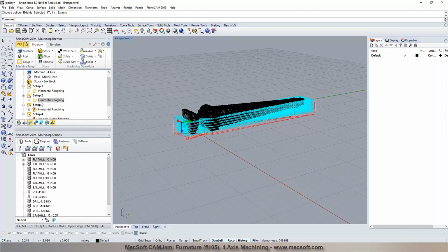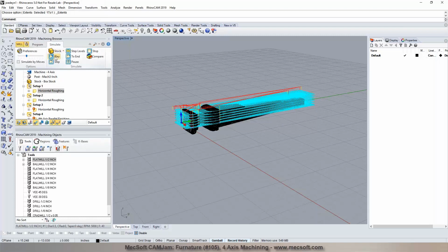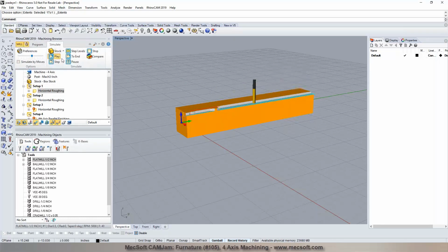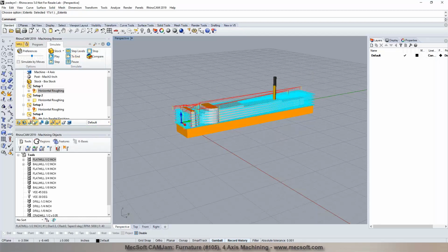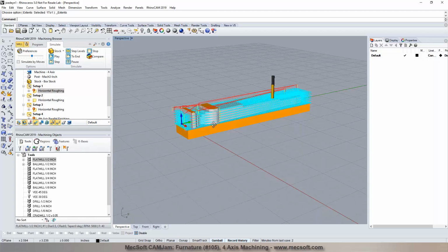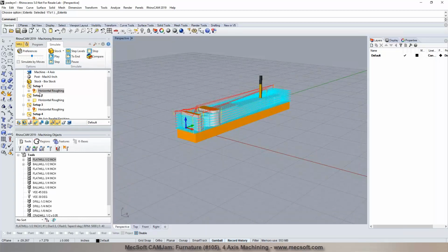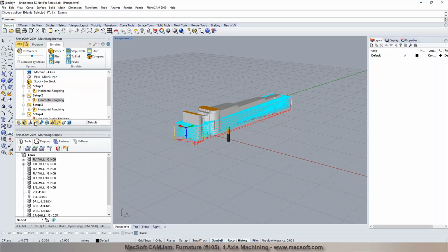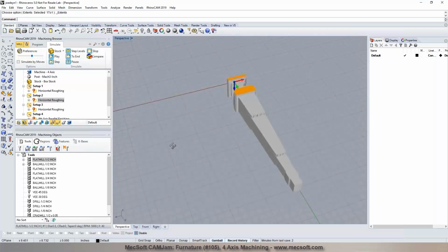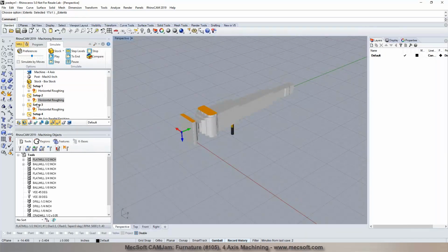So you're basically creating your template of operations for your workflow, and you'll now notice how easily you can adapt it to different operations. So you rough that in a three-axis rough. Yes. And then would you turn it, since they're all 4-sided, you turn it 4 times? I could just do it from 2 sides, because if there aren't any undercuts, you can just do it from 2 sides. Okay. And then I can go back and do the finishing operations in here.